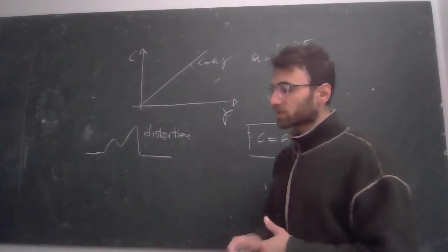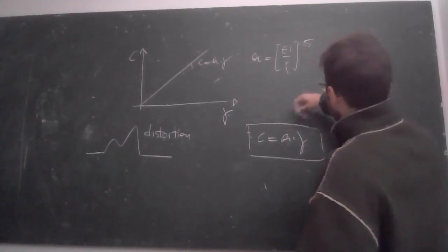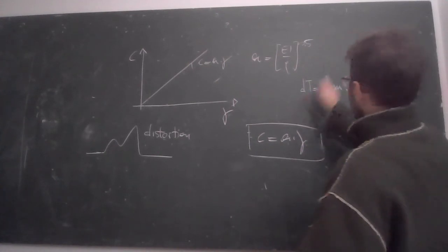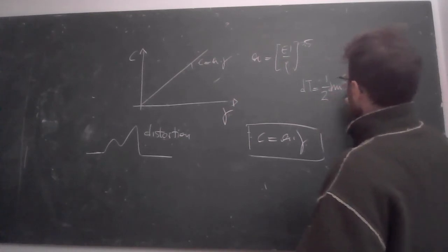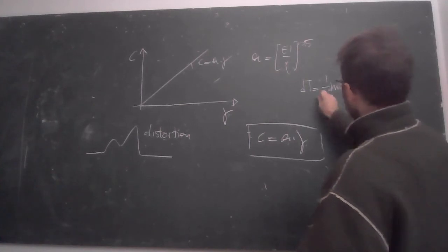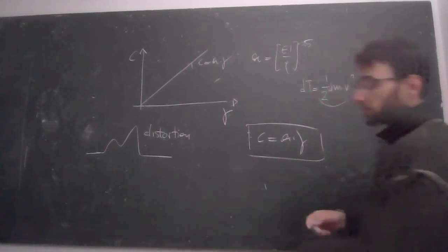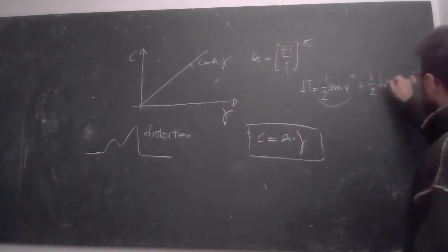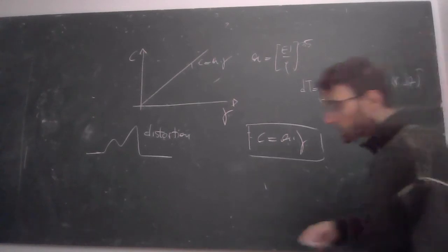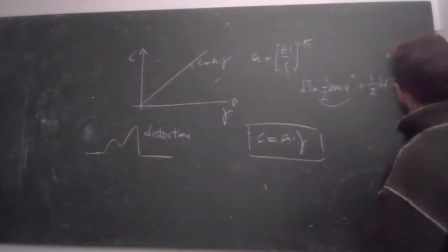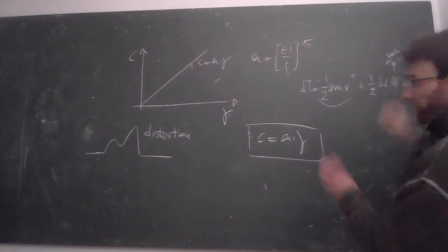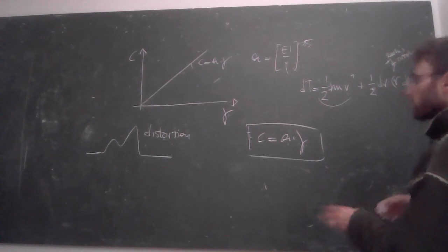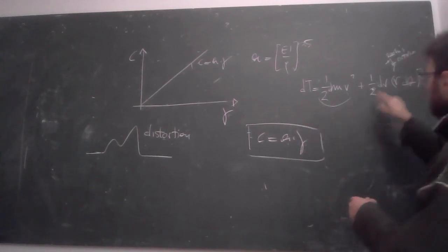But there is even another contribution that we are losing, which is when you consider the kinetic energy of an element. The kinetic energy is 1/2 dm v squared, where dm is the element of mass and v is the velocity. We are considering just the contribution of the vertical displacement. We are neglecting the rotary kinetic contribution, which is 1/2 dm (r dtheta) squared, where r is the radius of rotation of that element of the beam, and dtheta is the angle. So when theta is very small, we can neglect in the kinetic energy the contribution of rotation.